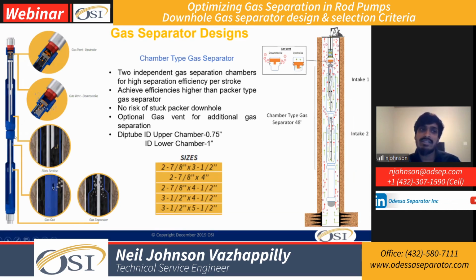Now let's think about having the same ID in the dip tube on both of these chambers. What is going to happen? The majority of the fluid is going to tend to go through the top chamber. Why? Because the energy consumed by the fluid is much lower traveling through this dip tube compared to this longer dip tube, which is almost twice as long.